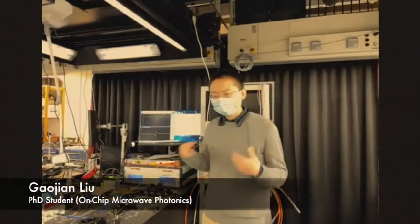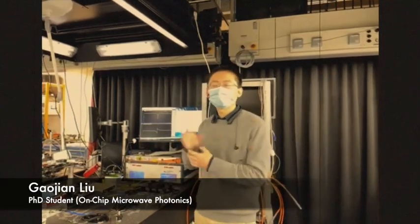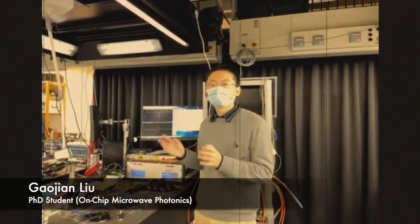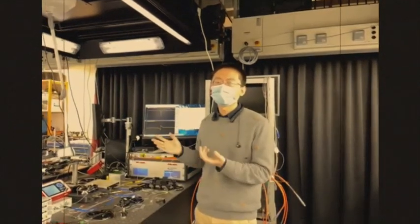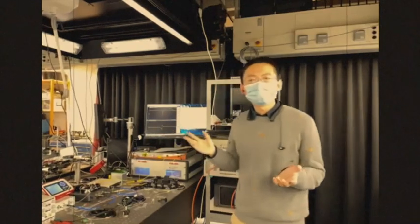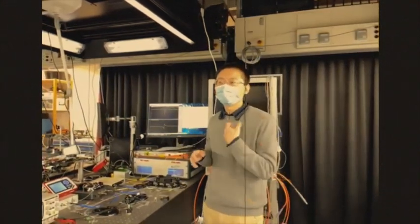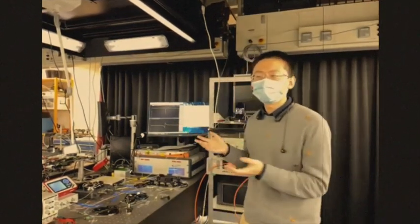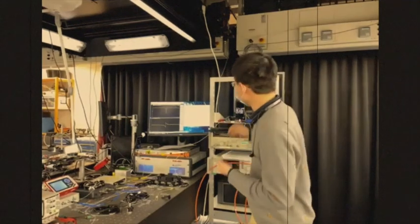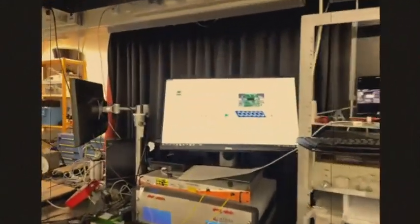Well, the idea is that we want to convert the RF signal into the optical domain and use some optical components and devices to process the signal, and then convert the signal back, retrieving the RF signal we want. The reason why we want to do it is that in the optical domain, we have large bandwidth and more flexibility in reconfiguring the response. Here, let me first show you the basic schematic of my setup.